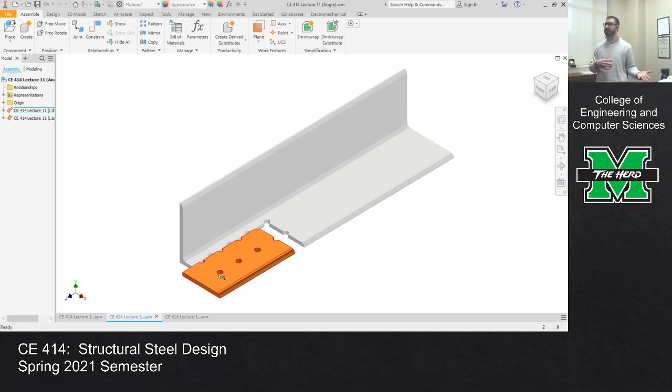One of the things you will see, and we'll talk about this more on Friday, is that you could have a situation where multiple failure paths could happen for block shear. But as we'll see in the math, sometimes some paths are more likely than others. To keep it simple, the path of least resistance tends to be the one that governs. What I mean by that is the following. Let me see if I can go back to my PowerPoint to explain.